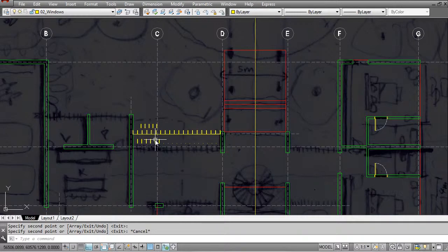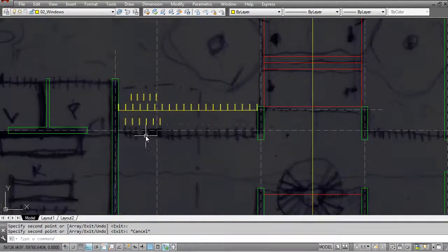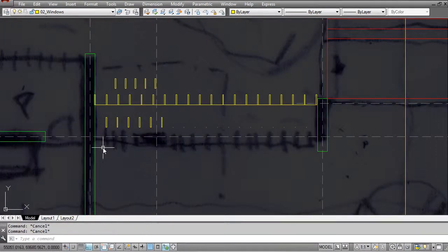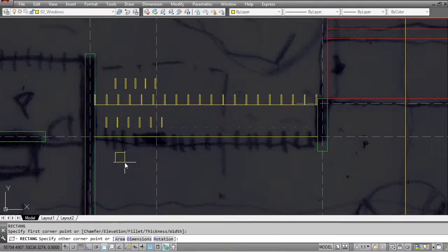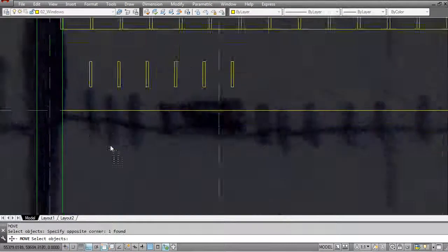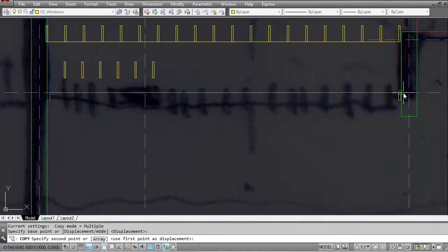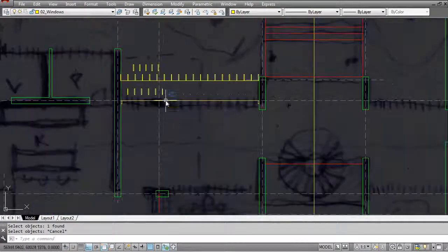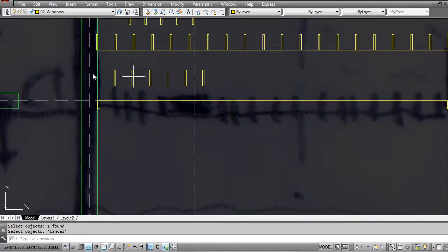What I'm going to do now off camera is I'm going to do something exactly like this, where I take a glass line, for example, like this. I'm going to then create main frames for the glass, so 50 by, let's say, 150. Then I'm going to create that glass line. So I'm going to basically just do this. I'm going to copy that across. This will be my main glass line. I will copy a few copies in between, so I will divide it, let's say, 3 or 4 times, and then I will add a screen to the outside.